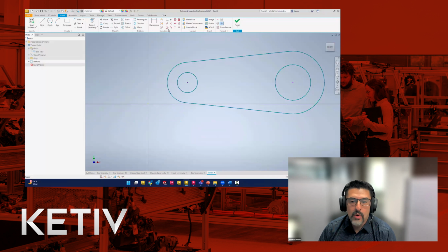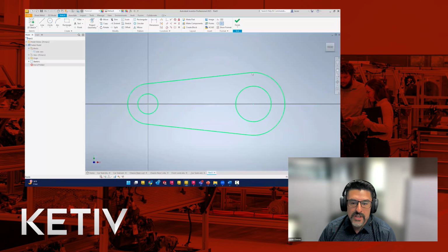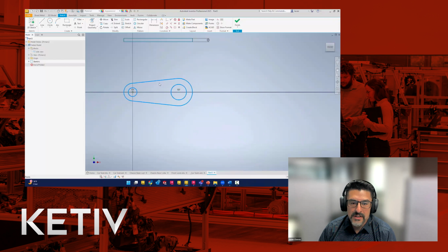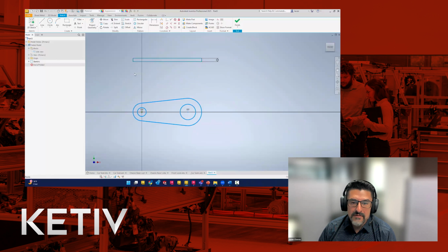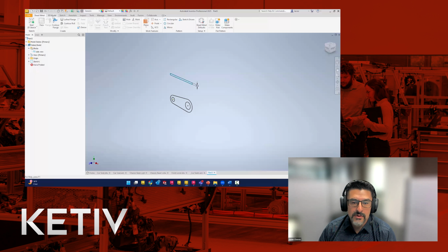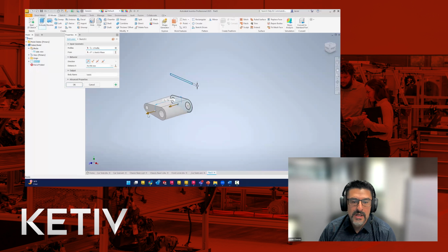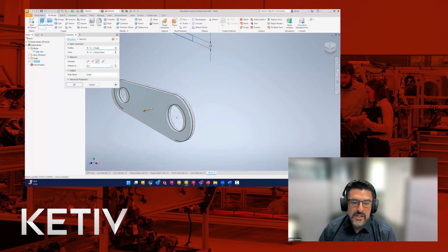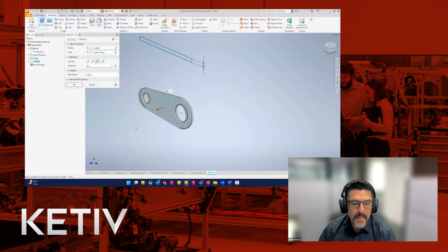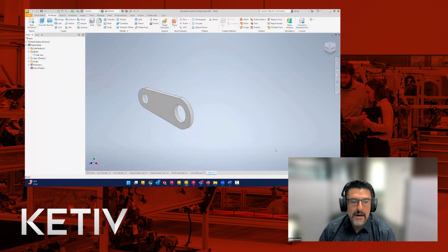So this is now quicker, because we don't have to constrain every single little thing. We're taking it and not changing it. Okay, so the top view, we're going to keep around for one specific reason. We're not going to extrude it. We're just going to extrude that front view. And when we decide how deep to extrude it, we can reference that other dimension. So that's just a little piece of knowledge you can take with you. If you do take other information, you can reference it. You can pick it from outside of that process.